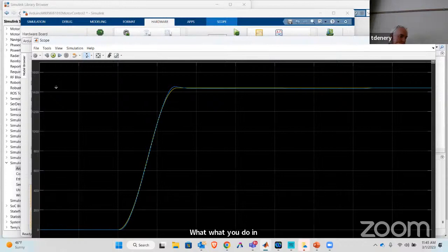He also talked about the torque and omega multiplied, being the equivalent to the electrical side. So this is related to the 305, 307. Then you're talking about the modeling. This is a coupled system. It's an electromechanical system, and we have magnetic system too. So we have the electrical world and the mechanical, and they make those ODEs. And this Simulink is actually solving these ODEs for us. What he showed us on the Simulink is part of those ODEs being solved. We put that on the hardware and we execute that.